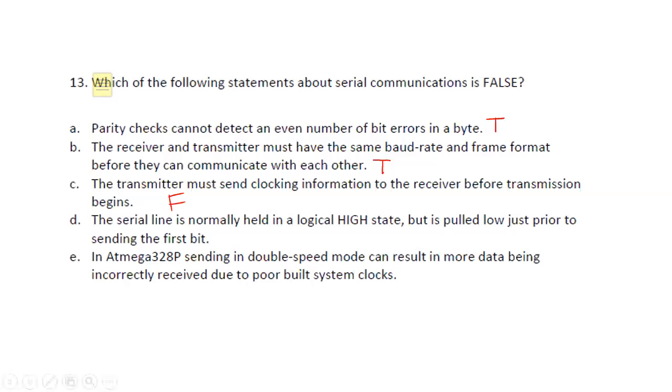There's a question here asking whether there is a specific type of frame format for error correction. There is no error correction here. The only thing we can do is error detection. With the current UART protocol, by just sending the data with odd or even parity, we can detect an error, but we cannot correct the error with that data alone.